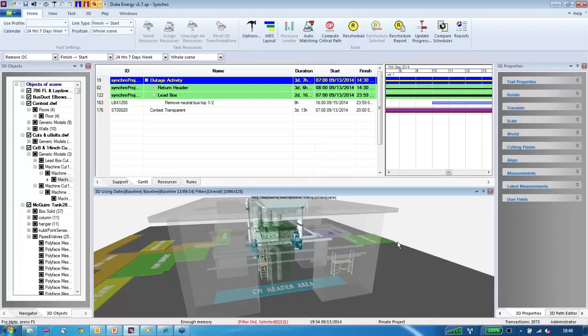Well, in Synchro, you can level by level select those doors going across. And if I have Synchro up now, if your 3D has been named correctly, and that's something I didn't talk about here because it wasn't really part of our effort for this scope, but if your 3D workflow is good, you can select all those, make a single click in Synchro, and it will create activities, and it'll even sequence them. So you say you're going to install the doors east to west, and then you can do it level by level, and you can very quickly build your schedule in Synchro based on 3D objects and bring that into P6. So it can actually be a time savings during schedule design.